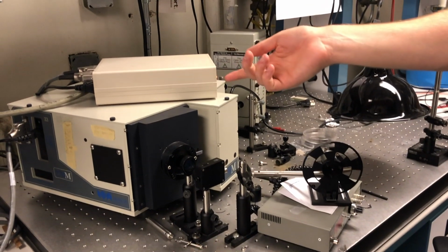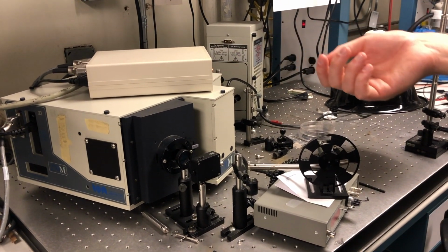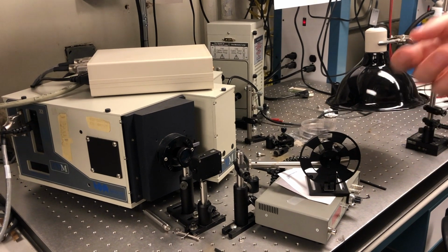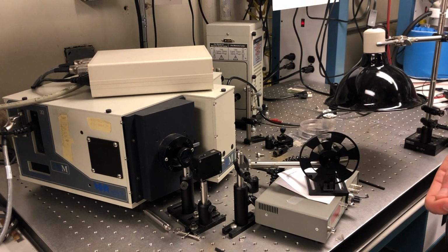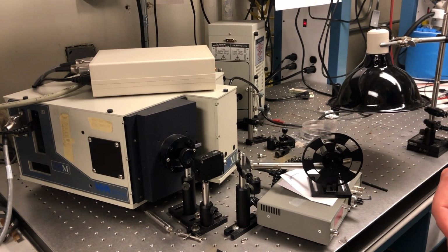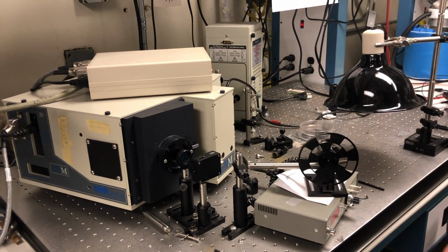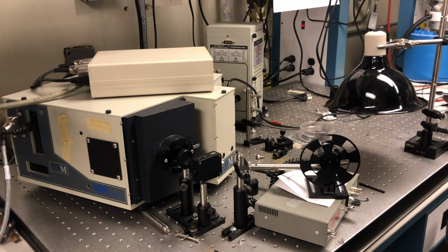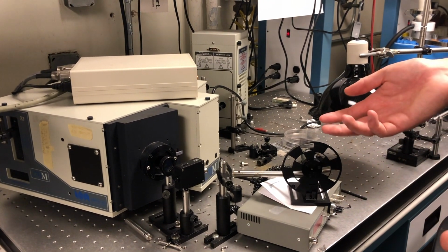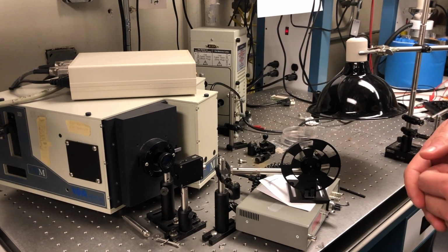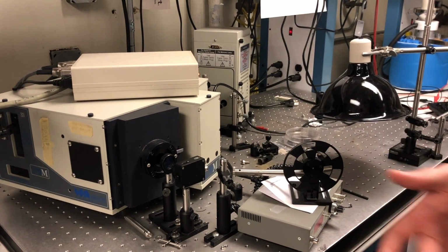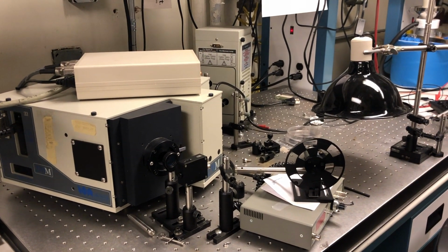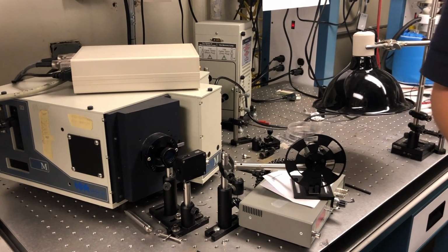But yeah, this is useful for, again, if you think your cell is not performing well in the blue, usually that means your front surface has an issue. If it's not performing well in the red region, usually your rear surface is having trouble. So you could have defects or other contamination, or you just didn't do a good job building the device. We won't run through that because it's not really set up, but basically you can chop your light into little pieces and measure the device at each one of those as well. And that should be all of the lab.